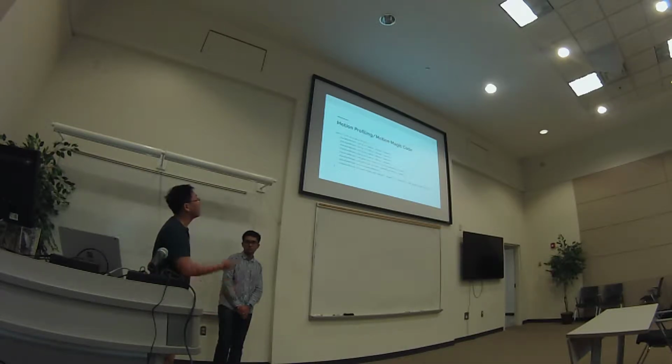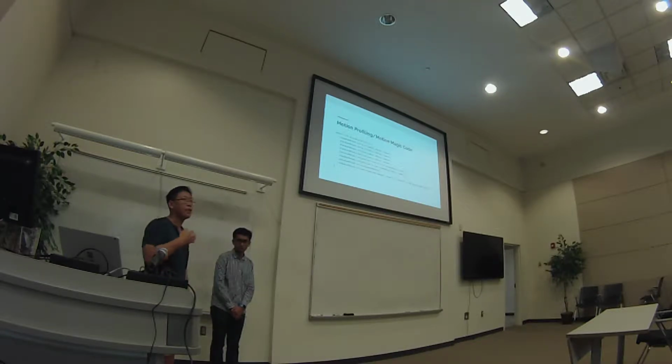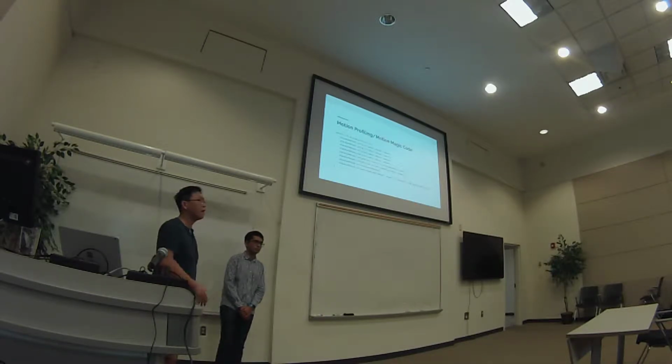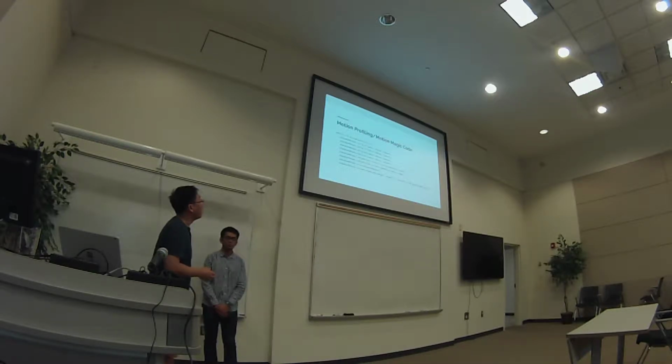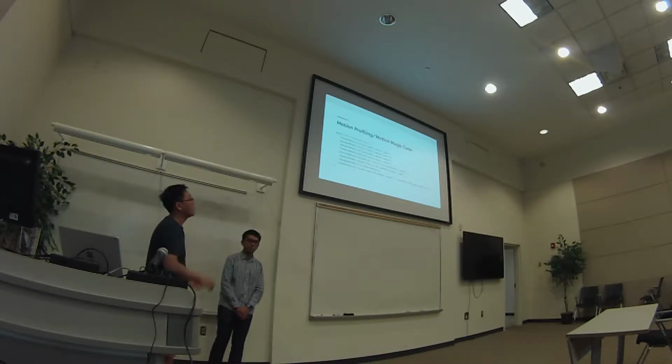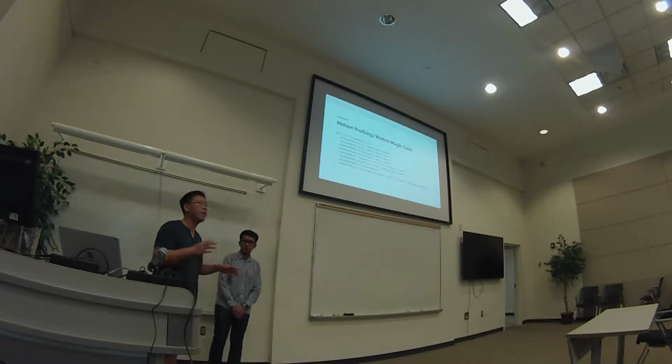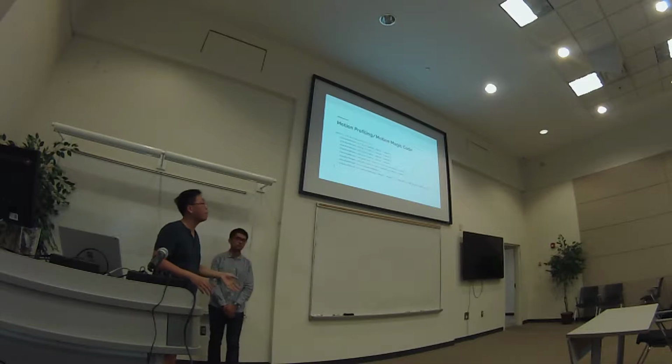You just set your PID gains again, and then you set your basic parameters of your mechanism, like your cruise velocity and your maximum acceleration that you want your mechanism to follow. And then again, we have a secondary motor here, and that's following the trajectory of the motion magic computed on the first Talon SRX. So you would have two Talon SRXs, but one would be following the first one.